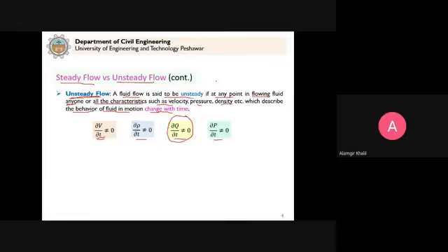We treat the velocity as one dimension, and we simplified our mathematical analysis, and it was very good because we can derive the formula very easily and understand everything very well. When we come to turbulent flow, the velocity is essentially three dimensional, and the analysis becomes very complex. And I told you that we do not have a 100% accurate model that can explain turbulent flows.